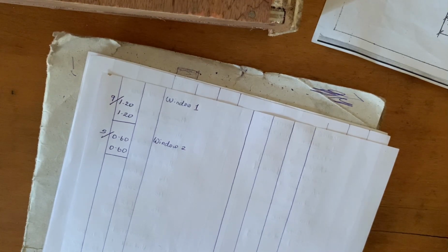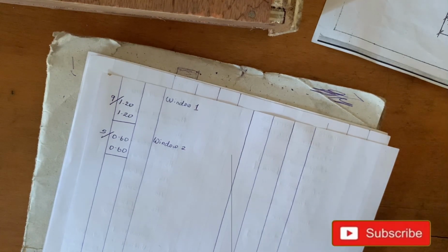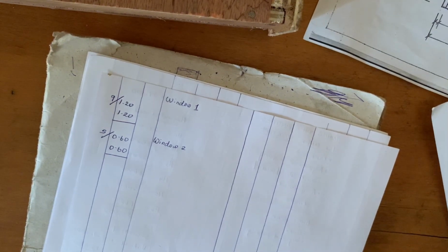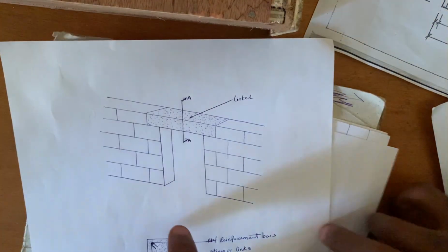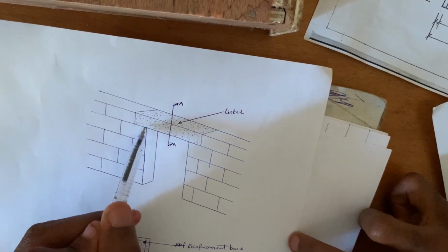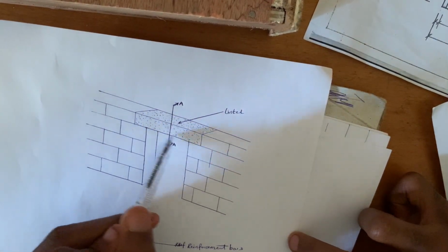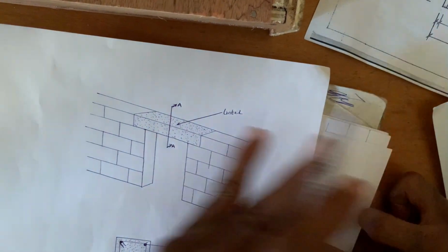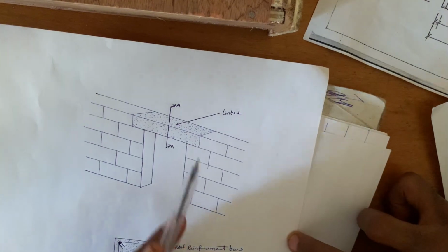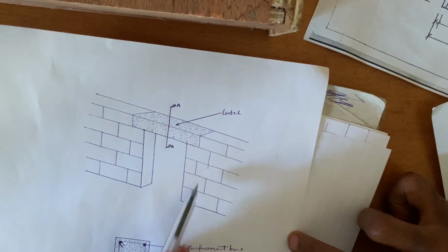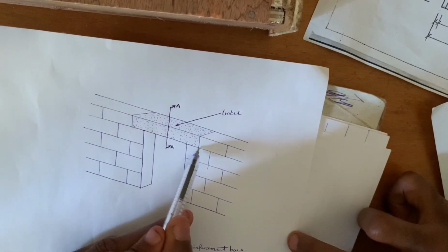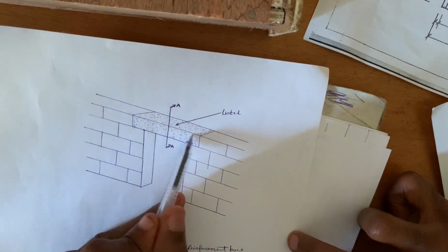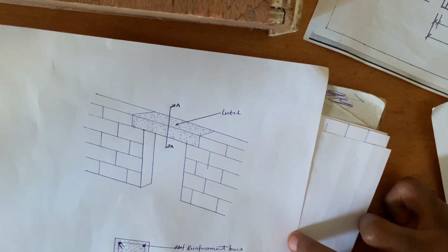However, these door and window openings are covered on top by what we call lintels. So we have to deduct for this space here for the lintel, because you know that everything is covered by block. So we want to deduct for the door, which we have already done, and the windows. Then we're going to also deduct for this space here to cater for the lintel. How do we do that?